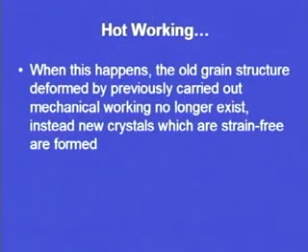When this happens, the old grain structure deformed by previously carried out mechanical working no longer exists. Whenever this recrystallization takes place, the old grain structure that was formed by previous cold working or hot working will no longer exist, and instead new crystals which are strain free are formed after the process of hot working.